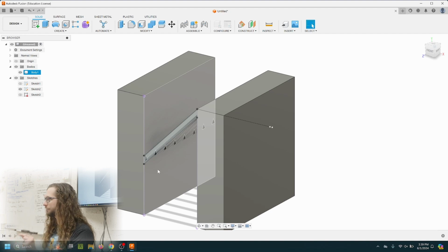They don't just have to be touching. If you make a path that goes into an object and use that join command, Fusion is smart enough to know that, even though it extends into my object, I can just ignore all of that, and the join will still just make it one solid object. If you use new body instead, it won't do that. It'll have an object that goes into another body in Fusion, and then you end up with similar things that happened in Blender, where if you try to put those in the slicer on top of each other, weird things might happen.